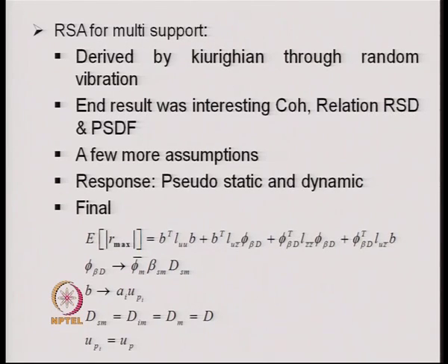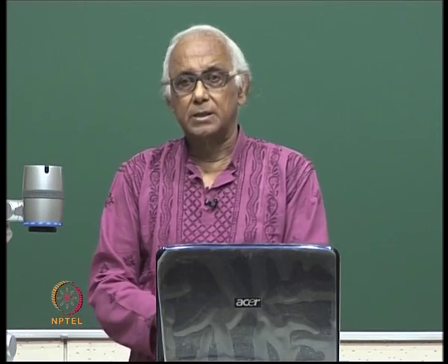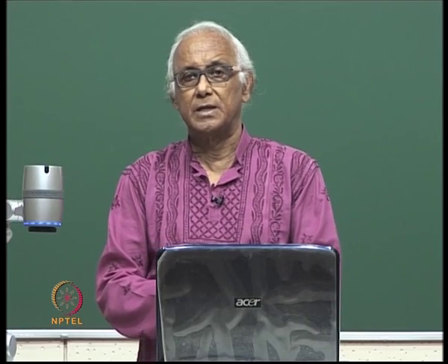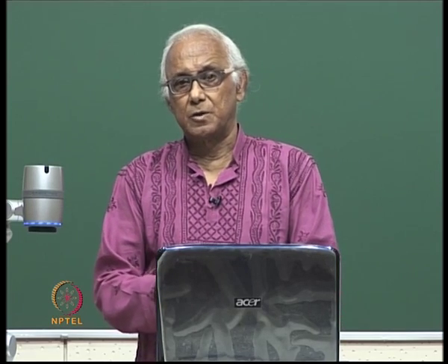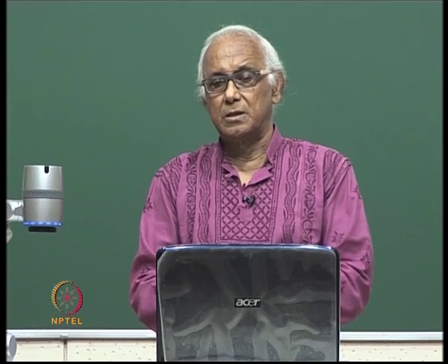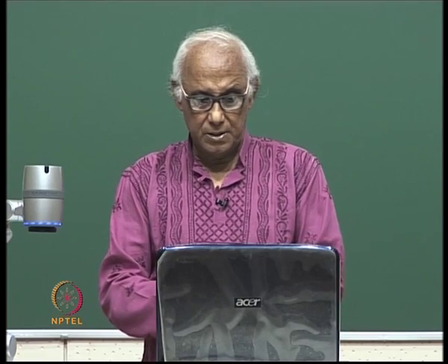After that, we discussed a response spectrum method of analysis extended for multi-support excitation. It was first derived by Der Kiureghian through a random vibration approach, but the end result was very interesting. It requires additionally a coherence function and the relationship between the response spectrum of displacement and the power spectral density function. Then we discussed how the response spectrum method of analysis can be utilized for secondary systems, and for non-classically damped systems.